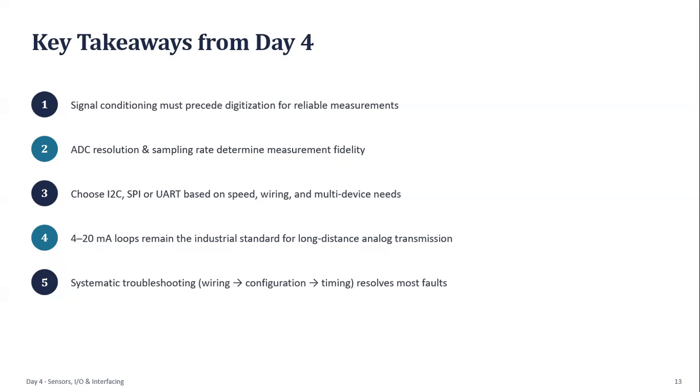Here are the key takeaways of the Day 4 Faculty Development Program. Let us summarize today's learning. Signal conditioning improves measurement reliability and quality. ADC resolution and sampling rate determine the digital measurement quality. Select the proper communication protocol standard, say I2C, SPI, or UART, according to the application requirements.